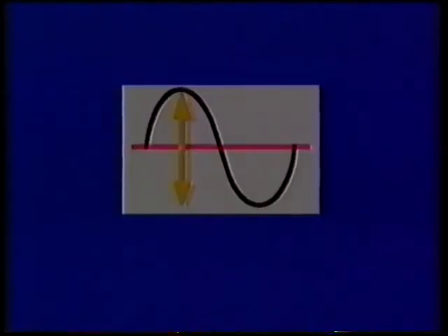Displacement can also be illustrated using a sine wave. On this sine wave, the center line represents the shaft's position at rest. The sine wave shows the displacement of the shaft first in one direction and then in the opposite direction as it completes a rotation. Here, it has returned to its rest position. Total displacement is the distance the shaft travels from its rest position during one revolution. So, total displacement is represented by the distance from one peak of the wave to the next peak.